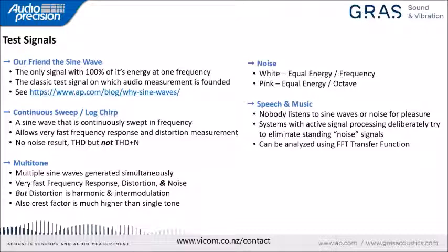And then we have pink noise. The main advantage of pink noise is that if you actually look at noise measurements in the real world, the natural world does not have flat noise with frequency. The natural world is actually dominated by low frequency noise. And what you generally see is a curve where the energy is equal per octave. And if we're looking at it on a spectrum analyzer, we'd see a decrease of energy approximating 6 dB per octave.